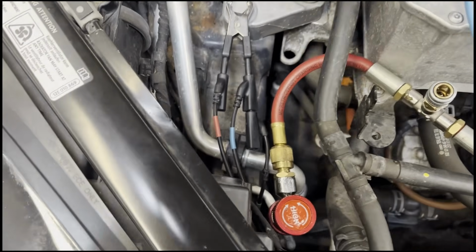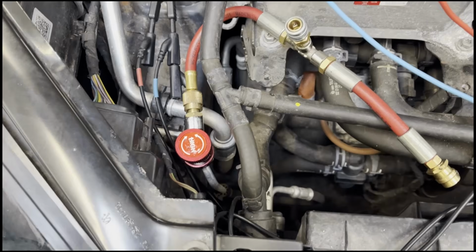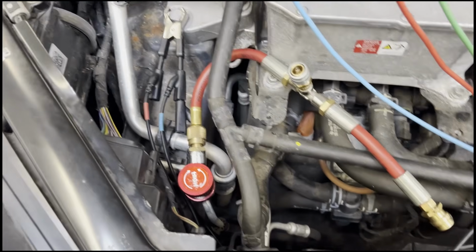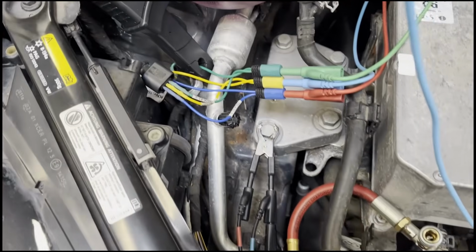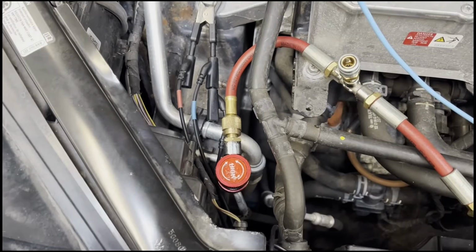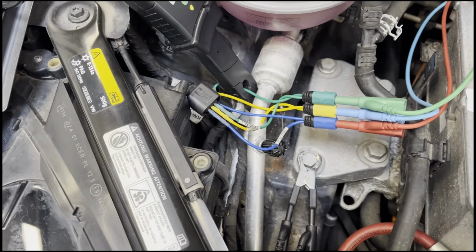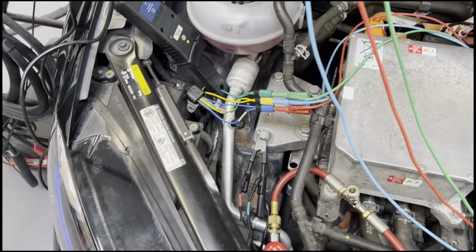Everything's referenced to ground, so all three cables reference to ground, and here you'll notice that we've got a pressure tap, something we've had made up on the high pressure circuit, so we can actually read the physical value with the transducer, and then later on cross-reference it with the LIN data that we've got from the sensor itself.